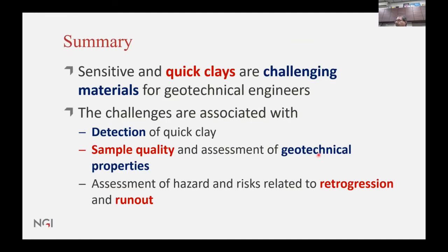So there was a short presentation that we have associated with sensitive quick clays in Norway. This is a very challenging material to work with for many geotechnical engineers. If we can summarize, maybe the challenges are associated with first the detection of these clays, also the sample quality and the assessment of the geotechnical properties. This goes together. And something that we are working quite a lot with at the moment is the hazard assessment and how to relate to the retrogression and the runout behavior of these slides.